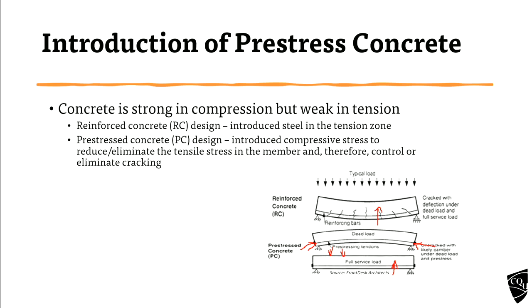Another advantage of small deflection: when the beam bends by a small deflection, the tensile stress at the bottom fiber will also be less, because the bending is less. So the chance of getting cracks will be less.